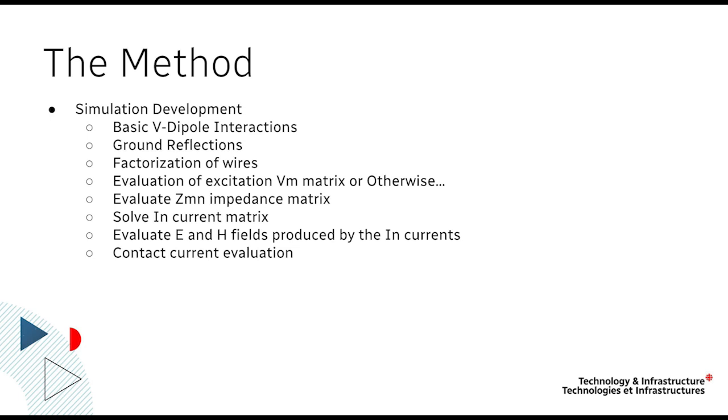Once you have your structure, I sometimes work fast and overlap wires, so the software will sort out the overlapping wires, keep only the non-overlapping ones, split the ones where there are intersections, and then simplify the solution. If you have a long string of wires with the same radius, it will recognize that they're all part of the same wire, remove the separation, and you'll have one long guy wire.